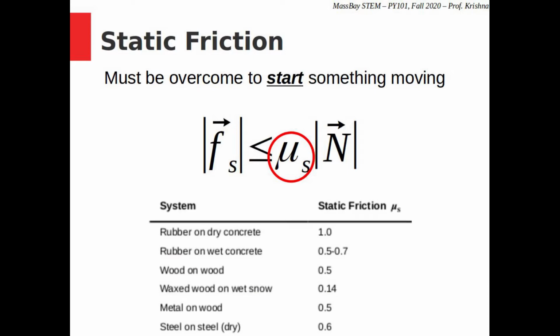Every pair of materials has a unique coefficient of static friction, and several pairs are listed in a table in your textbook. The coefficient of static friction for wood on ice happens to be 0.1. For wood on rubber, it's 0.9. For wood on wood, it's 0.5. These values are measured, or empirical. They are not easily derived.